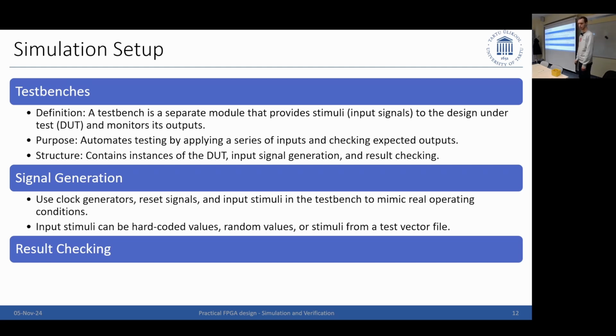For the signal generation, two obvious ones are the clock and the reset signals, unless you do not have a synchronous, clocked design, which is rare but can happen. For the last assignment, I tried to make it without a clock, but I was annoyed in the end, so I didn't. So clock and reset signals are always set up, but it's also very simple to do in the simulation, so that's not a problem. It can get more complex in the input stimuli.